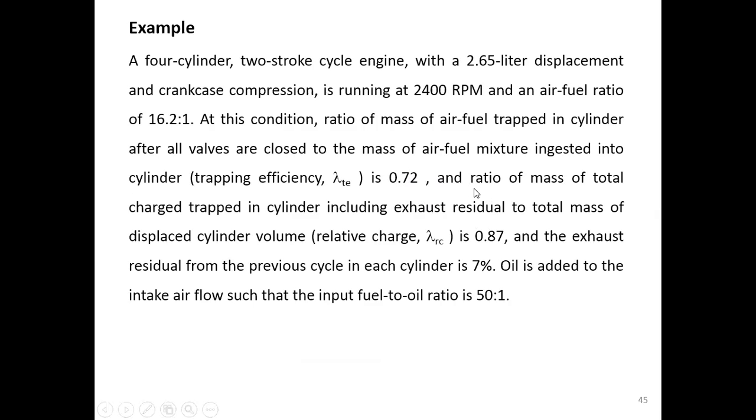And another ratio is what? The ratio of the mass of the total charge trapped in the cylinder, including the exhaust residual, to the total mass of the displaced cylinder volume. Now, they talk about two masses.